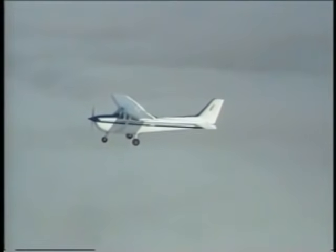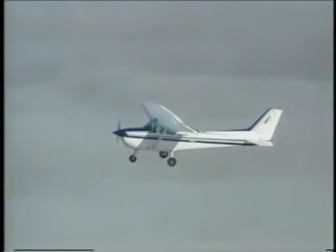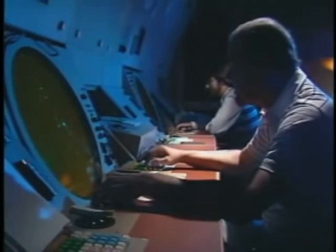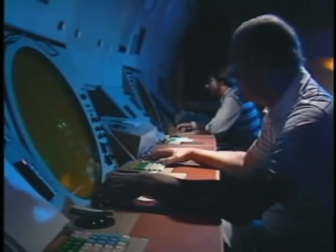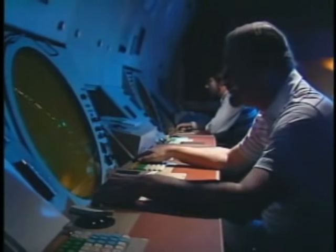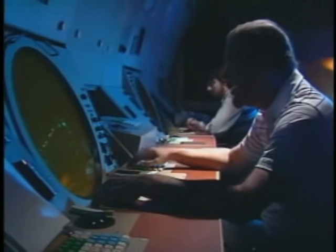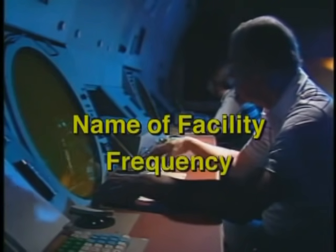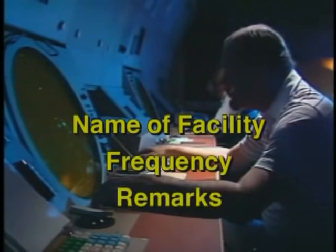Throughout most of your IFR flights, you are usually followed by some segment of the air traffic control system. On many cross countries, your flight will be handed off from departure control to an air route traffic control center. This handoff is usually accompanied by instructions which include the name of the next facility, the frequency, and any other pertinent information.